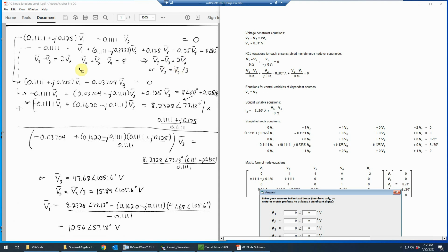Okay, so now let's substitute those results. And notice that now these equations have the vx, so we'll basically eliminate the v3 bar here and the v4 bar by substituting in. So let's start with this equation on top here. We'll just write that down here. So we have the original term for v1 bar, and then the v2 bar, remember, is v3 over 3. So I just divide this coefficient by 3, which I can do on my calculator. And it's basically minus 0.03704 to 4 digits times v3 now, because I'm using this to substitute in to get rid of the v2. And that's equal to 0.